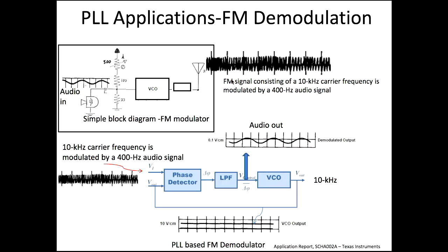demodulation. When PLL is used for frequency demodulation, please see that you are taking output from the output of the low pass filter. That's because the VCO output will usually be a clock frequency. That's the reason here you will get your audio signal.